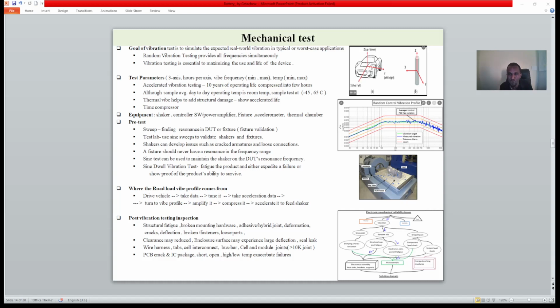It depends on where your part is located in the vehicle. Some don't have a lot of exposure, and some of them are sitting on the chassis, and they experience a lot of up and down. And check what's the frequency, between 2 to 100, or 2000, 300, depending on the vehicle.